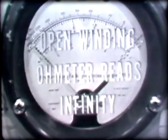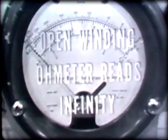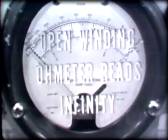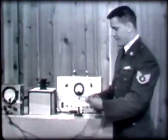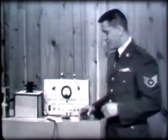We see then that an open transformer winding, primary or secondary, is indicated by a reading of infinity on an ohm meter. Now that brings us to the 300 turns winding. And since the 150 turns winding is open, then the 300 turns winding must be shorted. But let's go ahead and check it, see what indication we get.